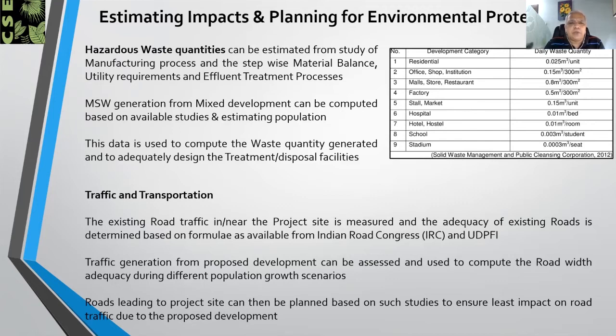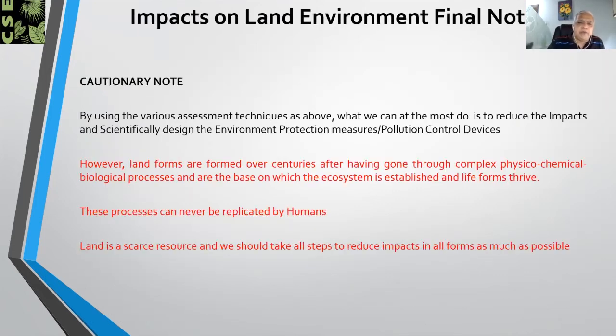Then we have municipal solid waste generation, which can also be easily computed from a mixed development, based upon the area and estimating the population, and then plans made for their safe treatment and disposal. Similarly, traffic generated from new projects, large area projects like ports, mining, greenfield airports generate huge amounts of traffic. And whether this traffic can be effectively dispersed, whether there are sufficient roads available to disperse this traffic, can be estimated by guidelines which are available from the Indian Road Congress or the UDPFI.